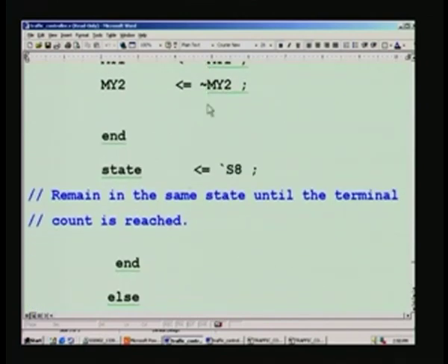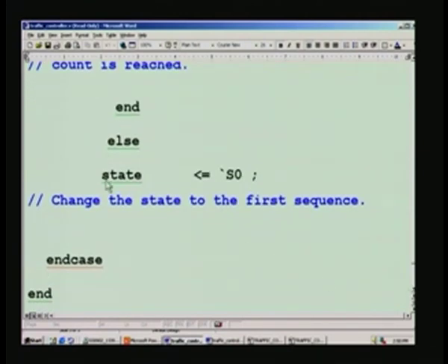So, if this is satisfied, then having done this, remain in the same state, SID state, so long as the blink is still 1, right. If blink is not 1, else will take effect. So, it will automatically take it to S0 state. That is what we said before, blink is also examined in S0 state, if you remember, and only at that particular state. Whenever it goes from SID state, it always lands up at S0 state. Similarly, at S0 state alone that blink is examined.